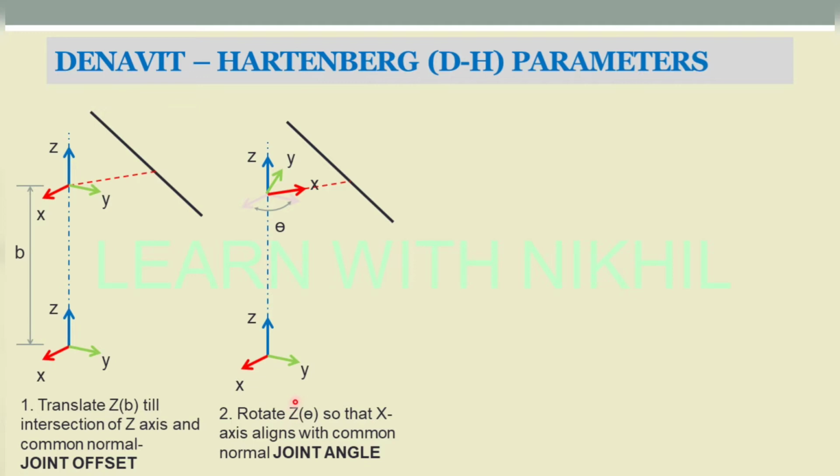When we rotate along Z, we write it as Z theta, so that the X axis aligns with the common normal. So in the first step we translated along Z to a height of B, that is called the joint offset. Next we rotated along the Z axis, which remains common, at an angle of theta, and that is called the joint angle.